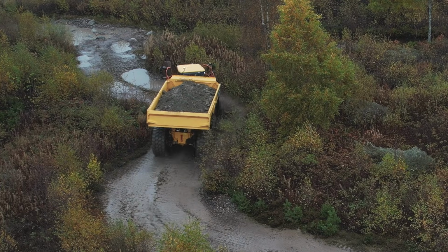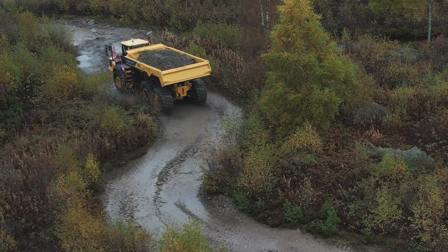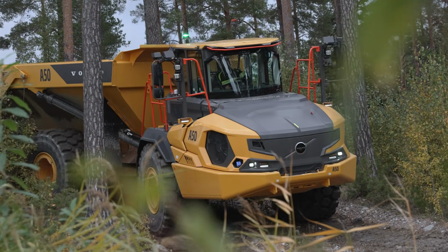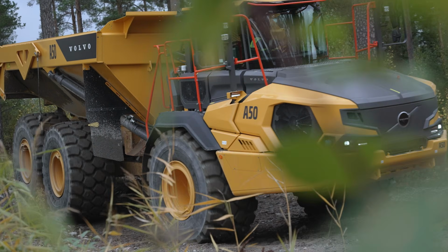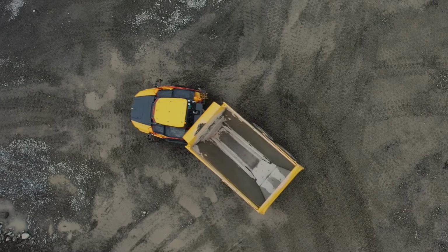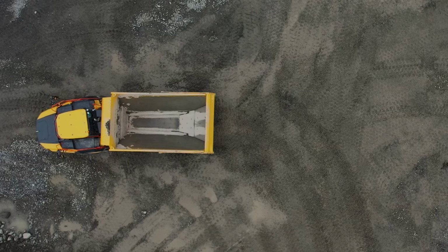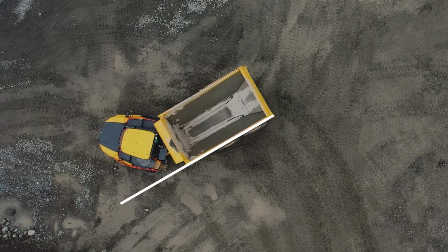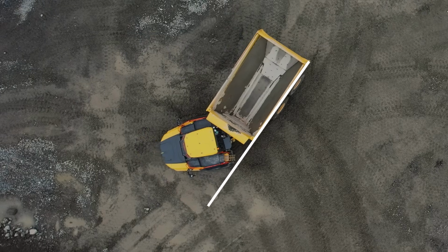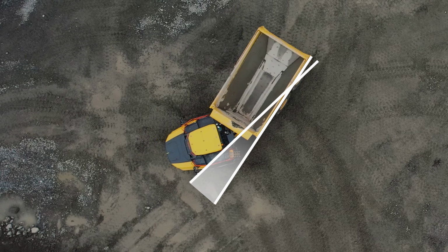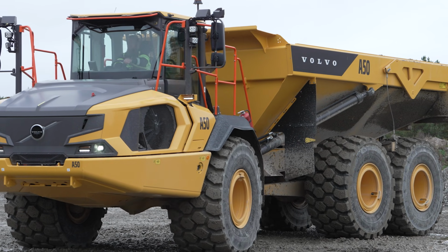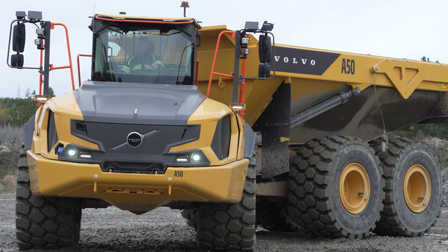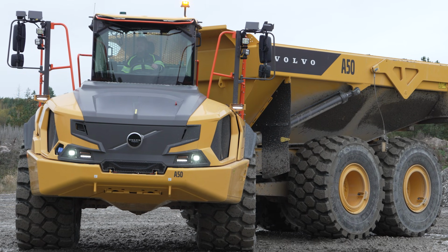The Volvo Articulated Hauler offers powerful and accurate steering. The hitch gives you a great off-road mobility without frame twist. When turning, make sure that nobody is standing close to the machine, as the machine folds at the hitch. It's also important to know that the front end of the trailer moves outwards when turning. Pay particularly close attention when operating in narrow, tight areas.